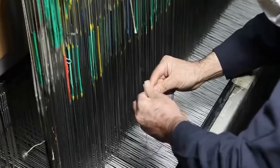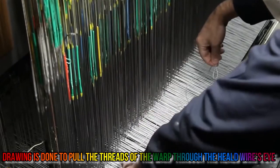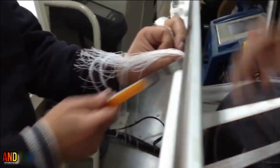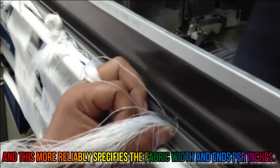Drawing. Drawing is done to pull the threads of the warp through the heddle wire's eye. Denting. Denting signifies drawing the warp thread through the dent as the reed plan requires, and this more reliably specifies the fabric width and ends per inch.